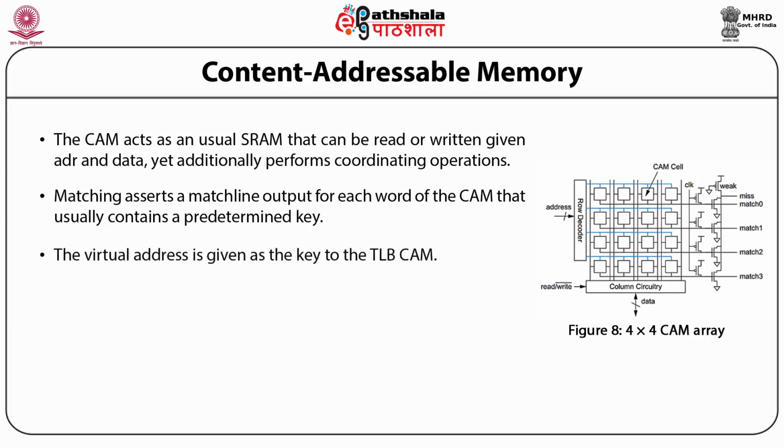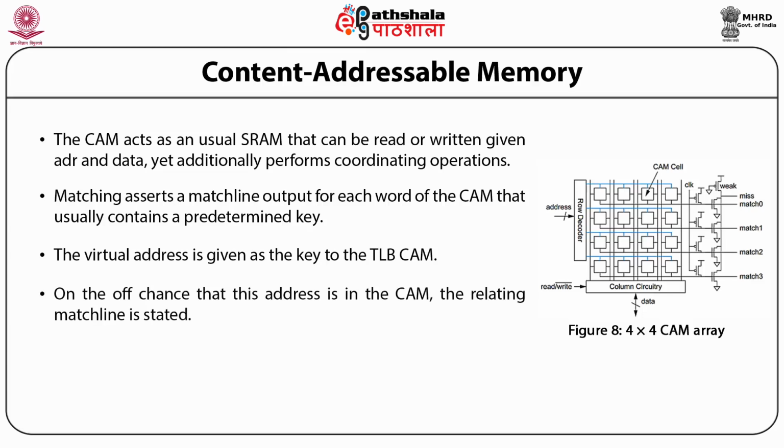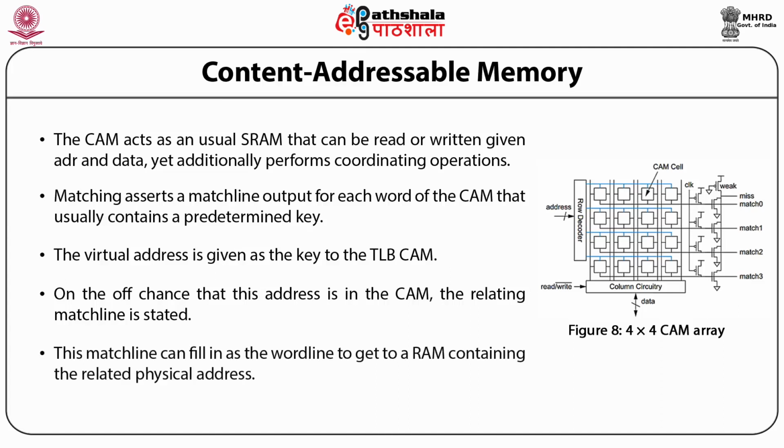The virtual address is given as the key to the TLB CAM. If this address is in the CAM, the corresponding match line is asserted. This match line can serve as the word line to access a RAM containing the related physical address.